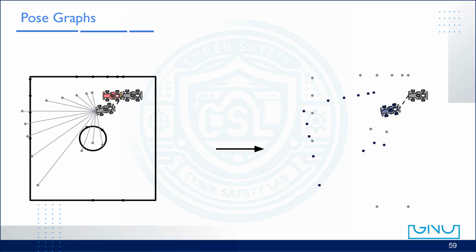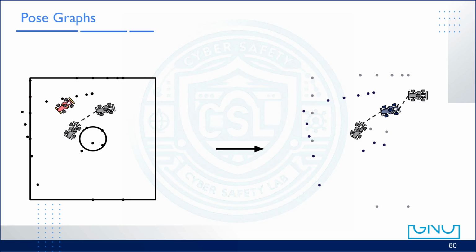The problem is not the measurements. The problem is the pose from which they are projected. Since the odometry-based pose is incorrect, the correct LiDAR points are placed in the wrong locations. This is why the map begins to look distorted. The measurements are right, but they are being drawn from the wrong pose. As odometry drift increases further, the mismatch between the scans and the real environment becomes more severe. The poses diverge from the true path, and the measurements continue piling up in the wrong places.